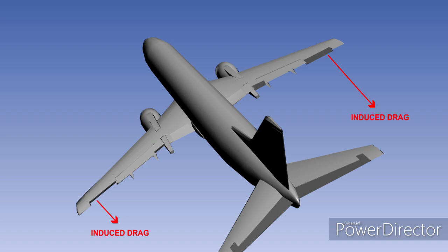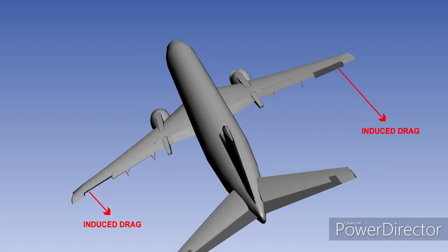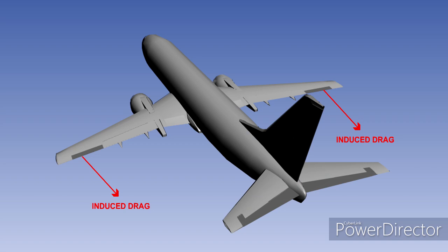The difference in drag on the two wings produces a yawing moment, which is opposite to the rolling moment. That is, a roll to the left produces a yawing moment to the right, and a roll to the right produces a yaw to the left. There are three main methods in common use to counteract this adverse yaw. They are differential ailerons, Frise ailerons, and aileron rudder coupling. We will now have a look at each of these methods.